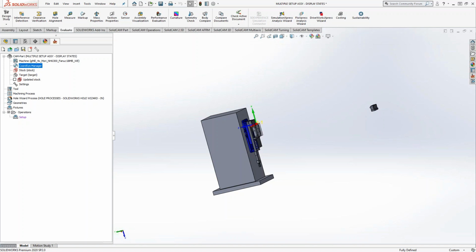Geometry tags is kind of what I think he's getting at. Exactly. I didn't call them geometry tags, but those ID numbers I mentioned earlier are those. That's exactly how SolidCAM is going to follow and remember what is to be hidden and shown, or in terms of SolidCAM, what it's going to remember to use as the geometry to stay up to date with, to be associative with. So every feature you choose, a solid edge or a face, has an ID number, or like Kevin called it, a geometry tag. That is what is actually assigned inside SolidCAM.